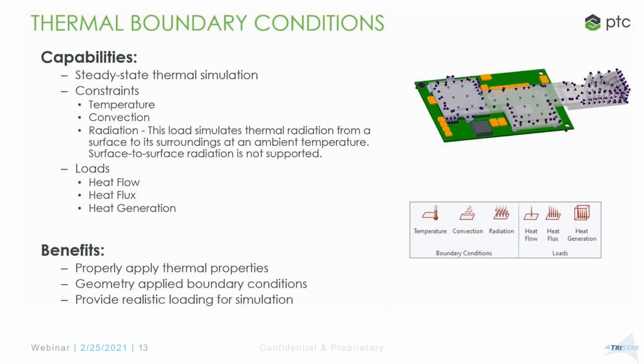If you want, you can do a CFD using our Creo Flow Analysis and then input that into Creo Simulate. That's the traditional process we've been doing, but inside of here, you're able to just use some empirical values for the convection heat transfer coefficient, apply the heat load, and then the radiation as well, right? Surface-to-surface radiation is not yet supported, maybe in the future, but you can assign the emissivity value in there, right? And then what it allows you to calculate is the temperature distribution, the heat flux, etc.